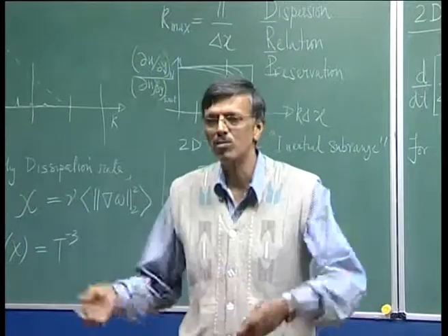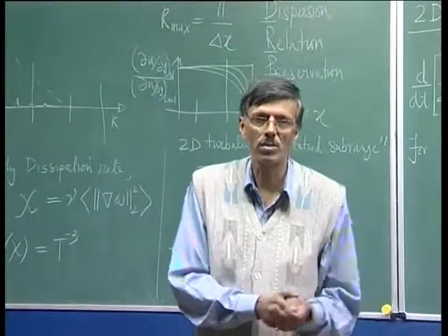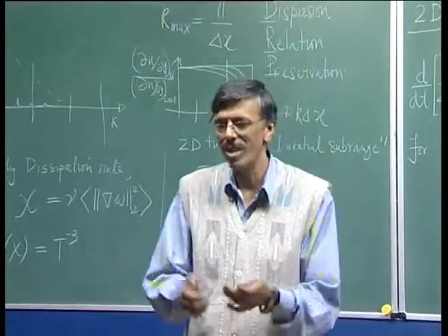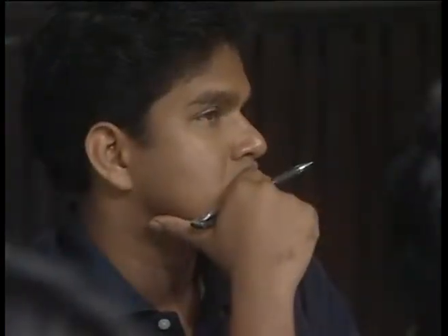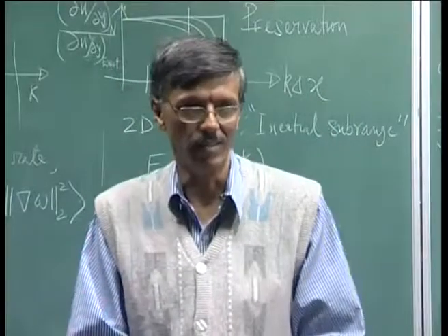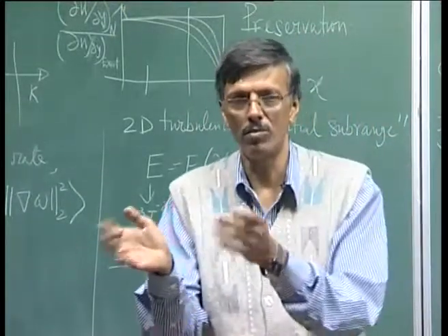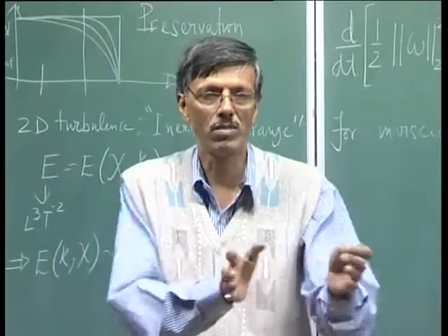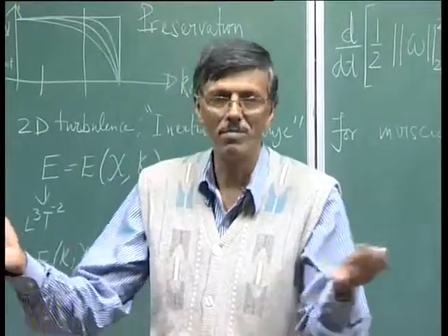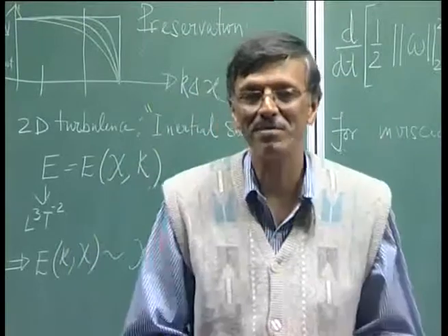We have explored a whole range of flows, starting from flow past a streamlined body to flow past bluff bodies. We are seeing that we could relate these POD modes with the instability modes, and we have come out with a point of view where we see some universal features appearing. Rajesh will tell you that if you compare flow past a cylinder, an external flow, versus flow inside a driven cavity, they may look completely different. But when you look at their POD modes, you will see those basic building blocks are identical.